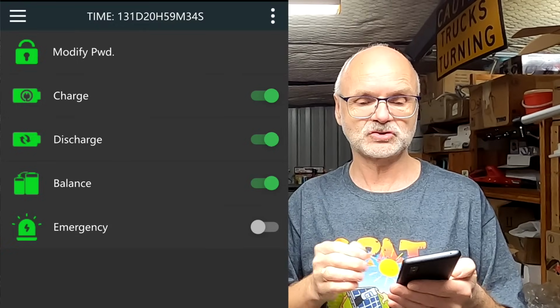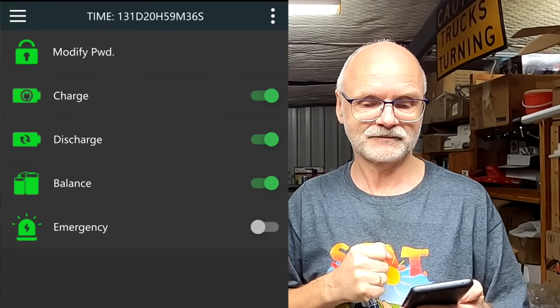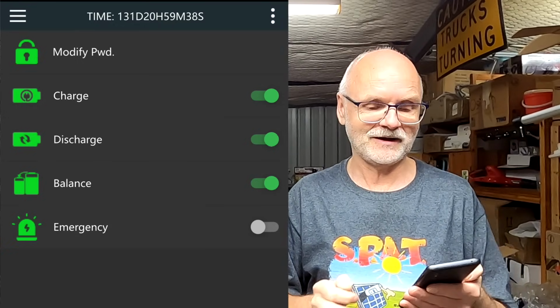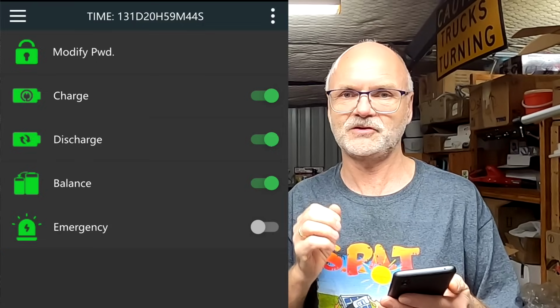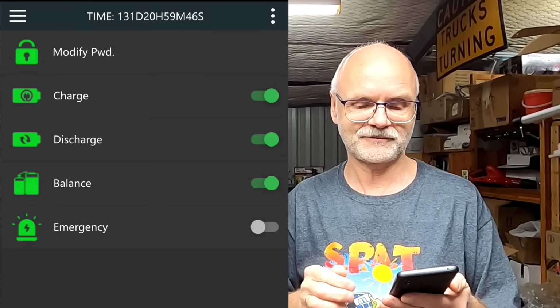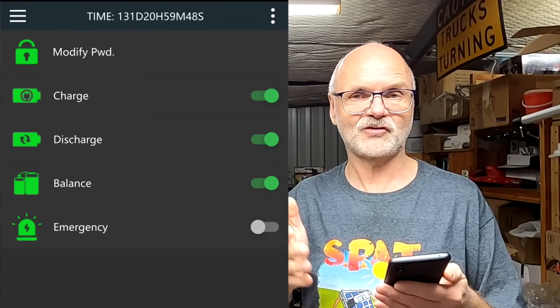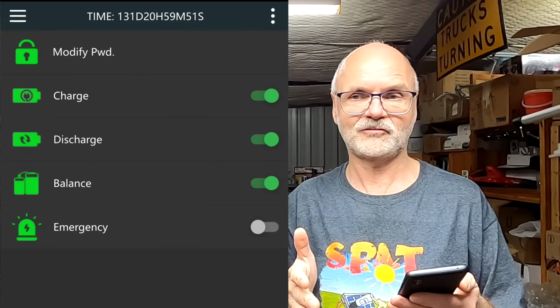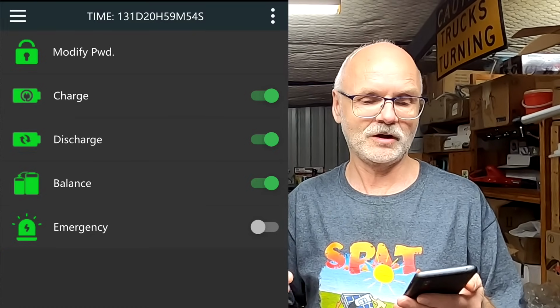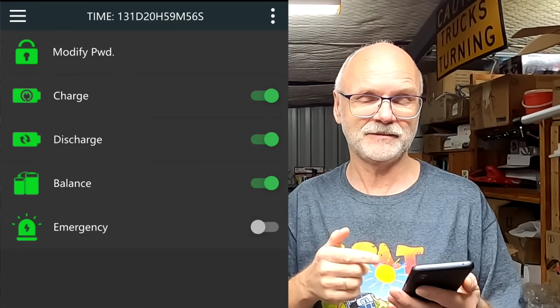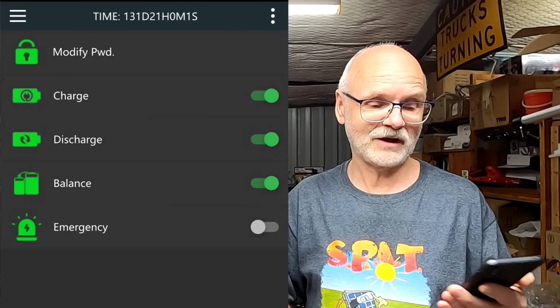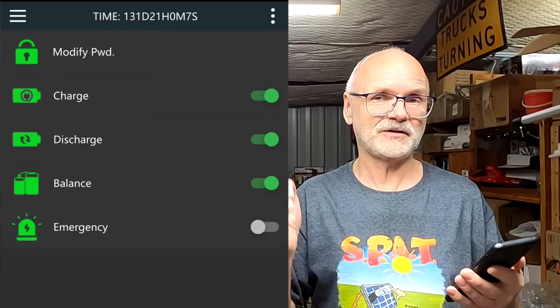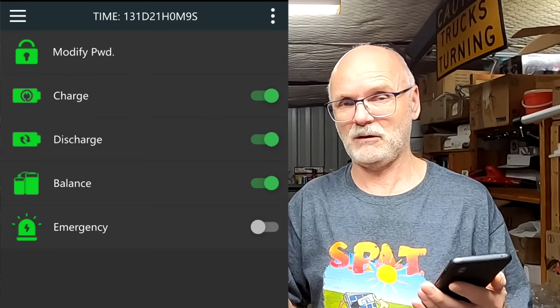And also with the new version now we have an emergency button here. And this is a very interesting feature. I wasn't sure quite what that actually is, but this is actually overriding your security switches of the BMS. So if your BMS has turned off because the battery is fully depleted to protect your battery and has turned off your inverter, you can flick the emergency switch here and it actually turns the battery back on. So in an emergency situation, that's why it's called emergency probably, you can actually deeper discharge your battery if you still need the power, right?